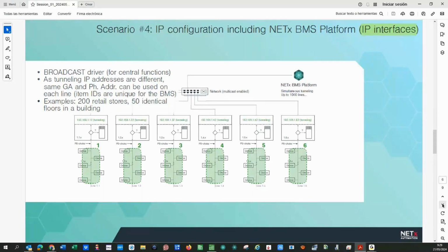On the other hand, we are using the tunneling connection. So this means that we maybe don't need the routing multicast connection. There are specific devices in KNX that are IP interfaces, not IP routers, that only provide tunneling connection. For us, they are enough. In many projects, we do not need routing multicast.